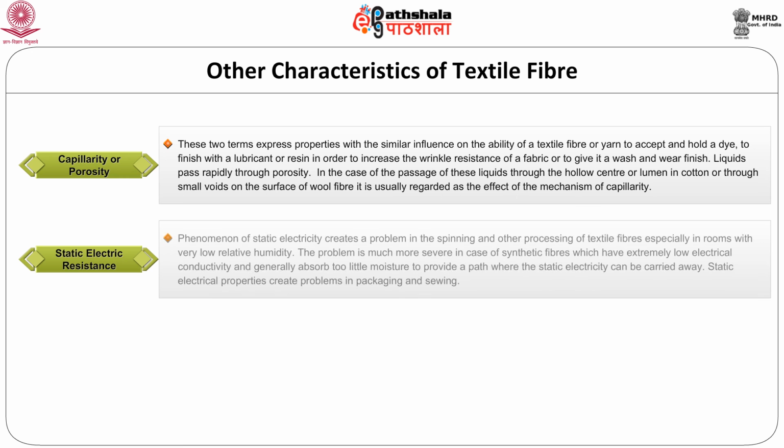Static electric resistance. Phenomenon of static electricity creates a problem in the spinning and other processing of textile fibers, especially in rooms with very low relative humidity. The problem is much more severe in case of synthetic fibers, which have extremely low electrical conductivity and generally absorb too little moisture to provide a path where static electricity can be carried away. Static electrical properties create problems in packaging and sewing.